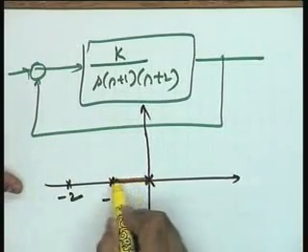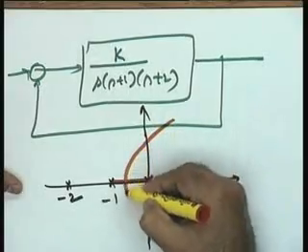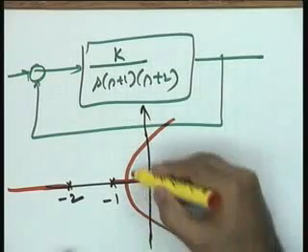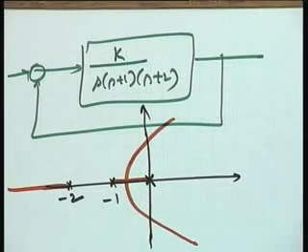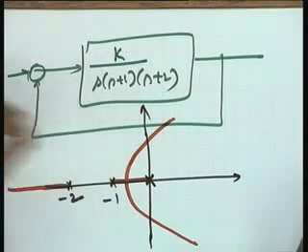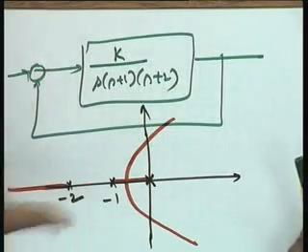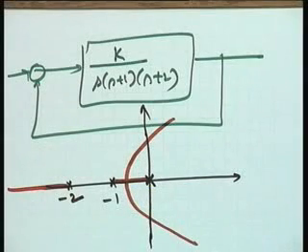But the root locus, as I know, will be of this nature. Please see, these are the root locus branches. This is the total root locus diagram. You can imagine that you will write the characteristic equation of the system, vary k from 0 to infinity, get the roots and plot them and join them by a line. If you do this exercise, the red lines will come. Okay? At this point, I hope you won't mind accepting this statement. Now let us see the conclusion. The conclusion is very visible from here.